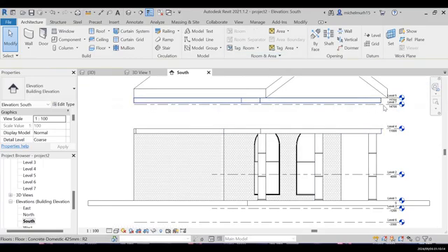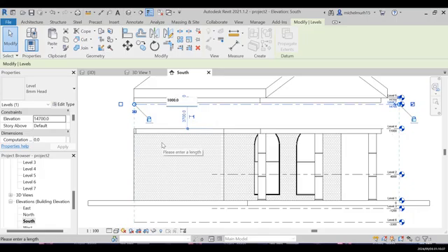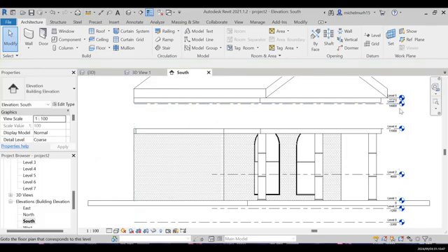If I click on the line here, I'm going to be able to modify the distance. You can see the distance between level 4 and level 7 is this one here, 3.7, and the other one is 1000. I'm going to change this into 900, so I'm going to make it shorter. Then I'm going to click OK. All right, so I modified the height of my level 7.